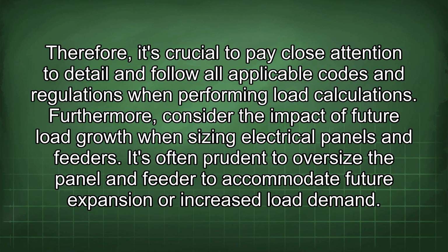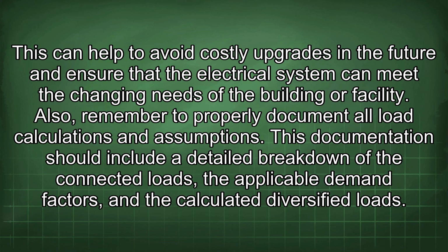Furthermore, consider the impact of future load growth when sizing electrical panels and feeders. It's often prudent to oversize the panel and feeder to accommodate future expansion or increased load demand. This can help to avoid costly upgrades in the future and ensure that the electrical system can meet the changing needs of the building or facility.